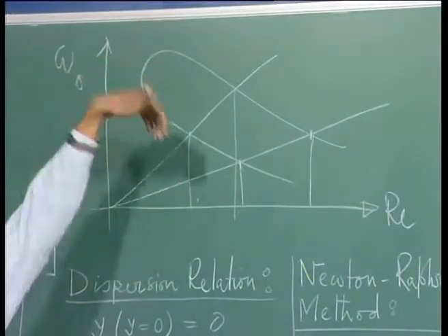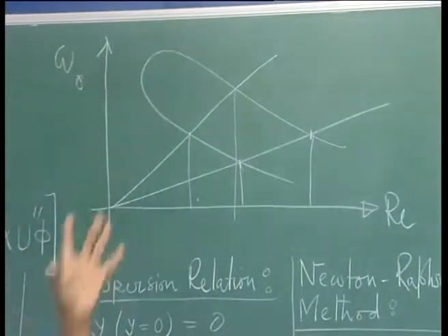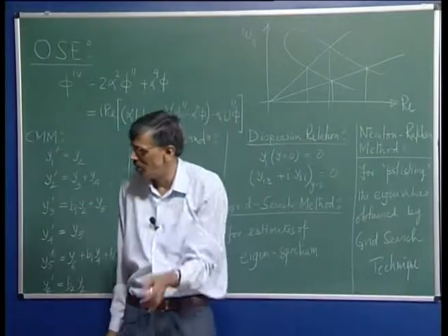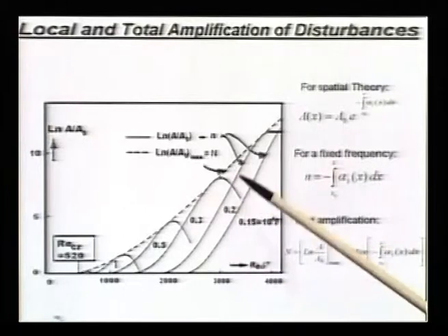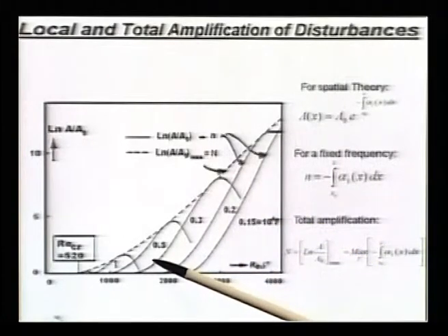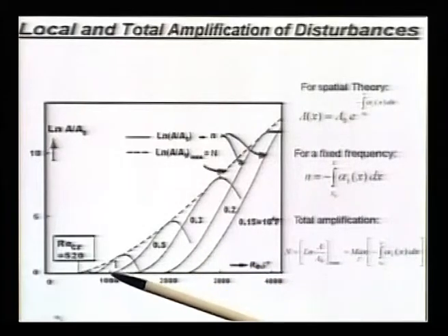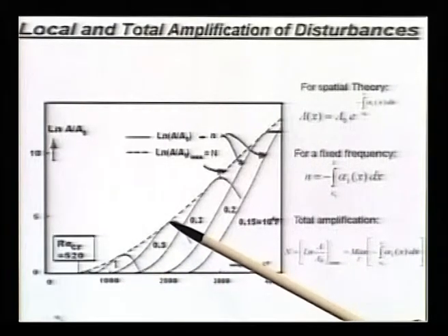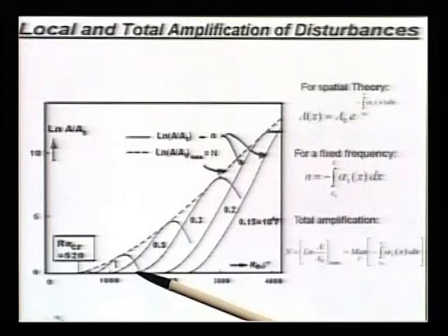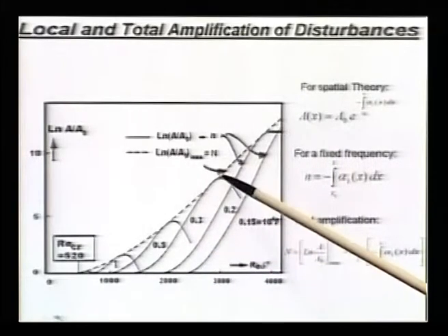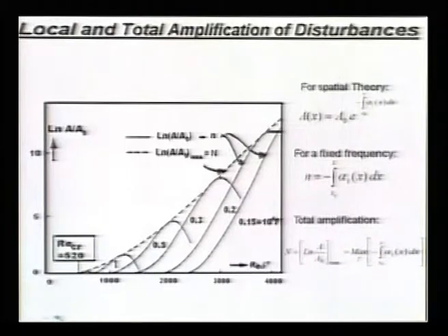And what we notice also, because the range, basically we are taking a horizontal projection of this. So, the extent is going to come down, and that is what you are also seeing, that as your frequency is increasing, the extent of the unstable band is decreasing. So, for this it is about from 1000 to here, for this it is about, let us say, 1300, 1400, all the way up to about 2400, 500 of that kind. So, this is the story that we are going to envisage.